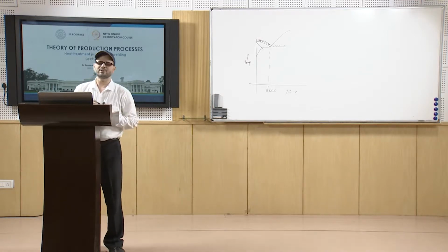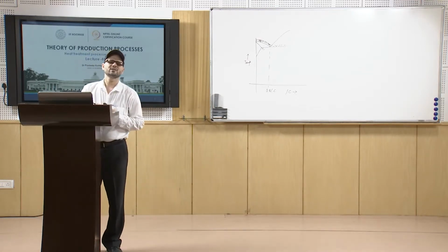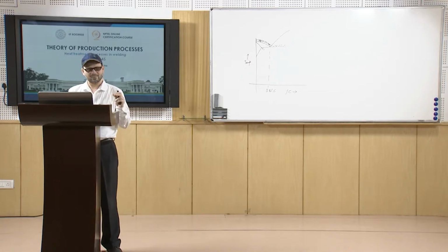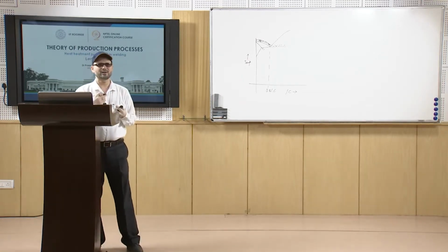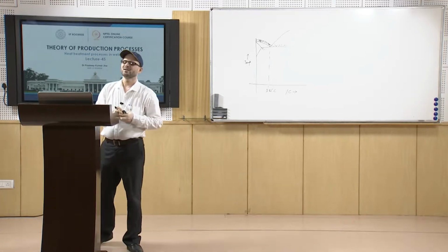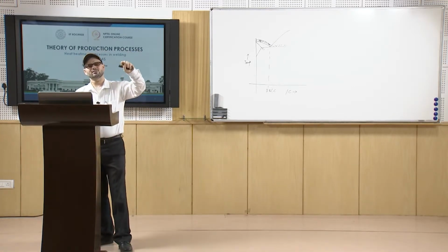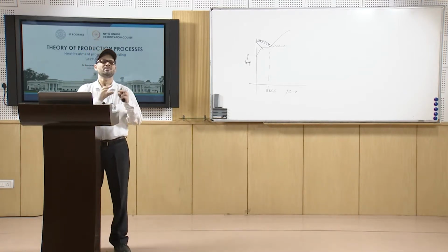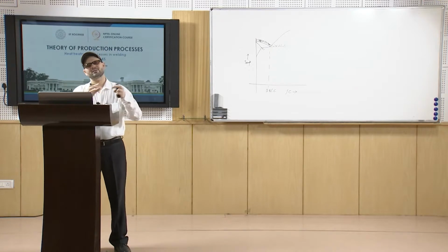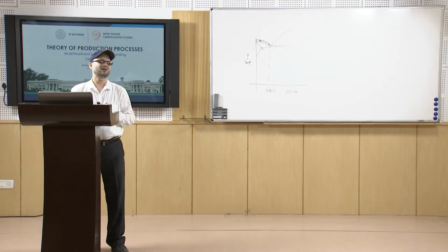Now, the holding time is 2.5 minutes per mm thickness of the plate. So, once you have a plate which you are welding, then depending upon the thickness of the plate, you will have about 2.5 minutes per mm section thickness you are holding.